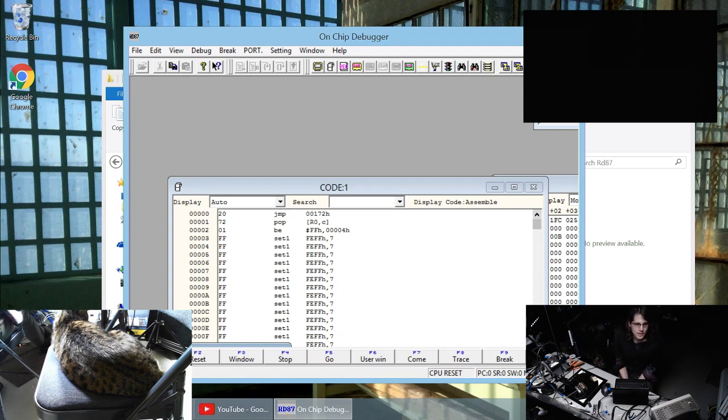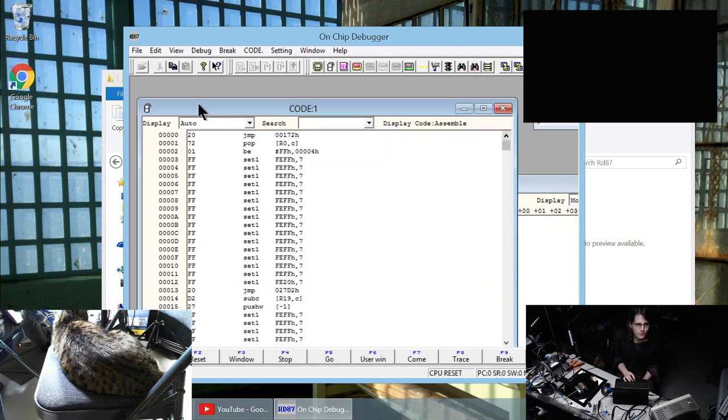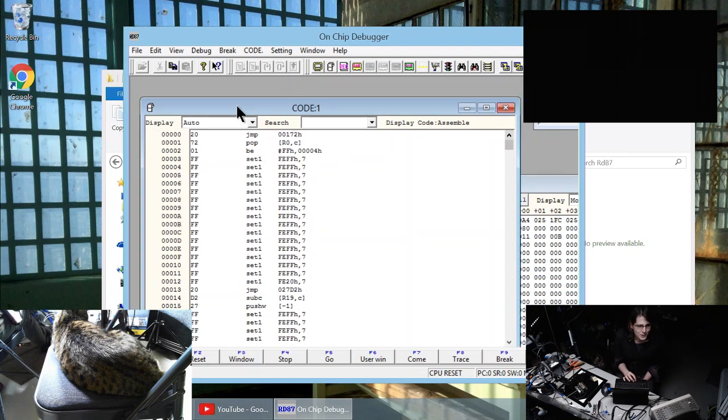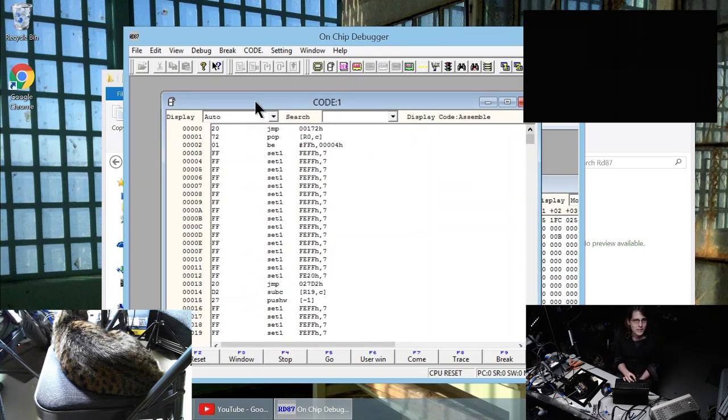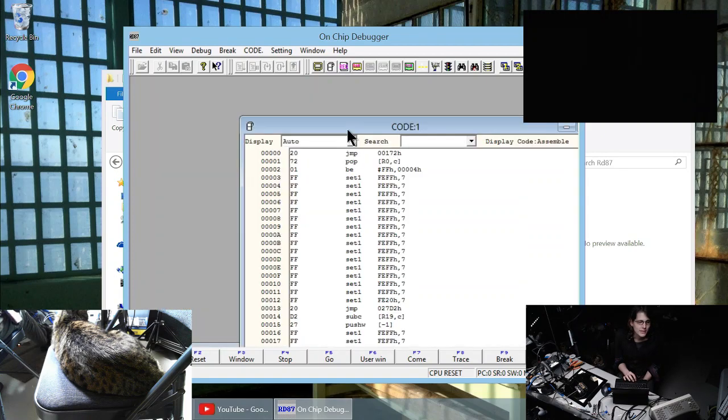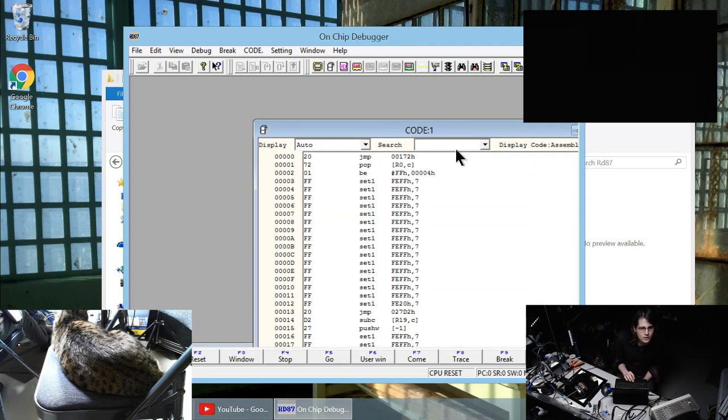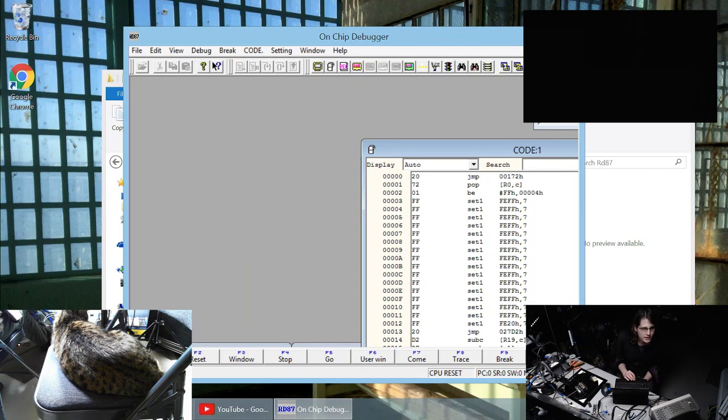So in the interrupt vector table, that's where the hardware will just branch the processor to a particular address when an event needs handling. And those numbers tend to be, at least on this processor, not really, like they won't really automatically synchronize most of the time. If you just start unassembling the code at the beginning, you won't really get a clean interrupt vector table. So you have to specifically line it up at several points most of the time.